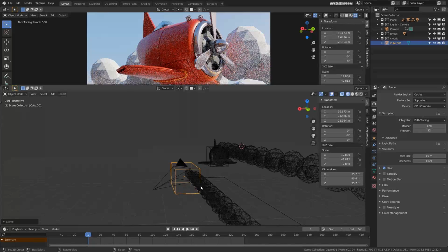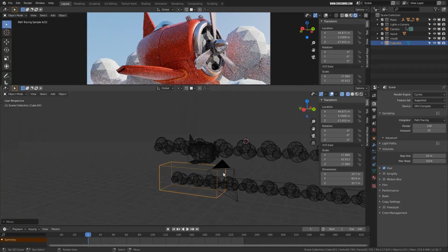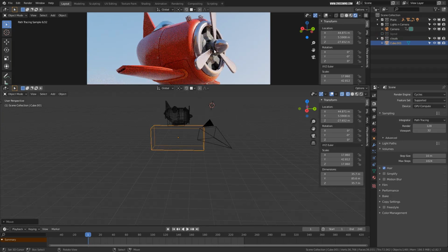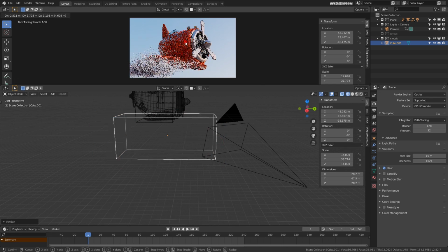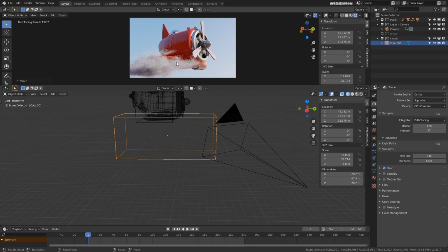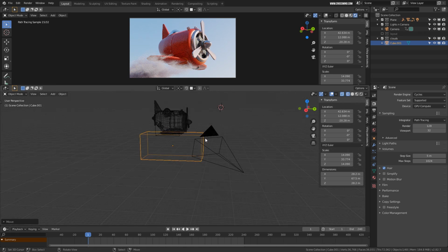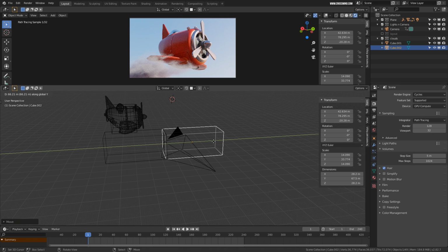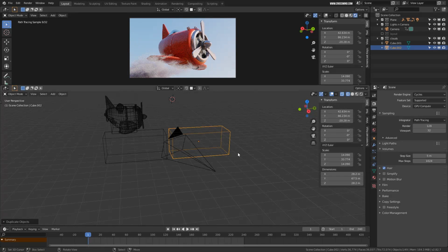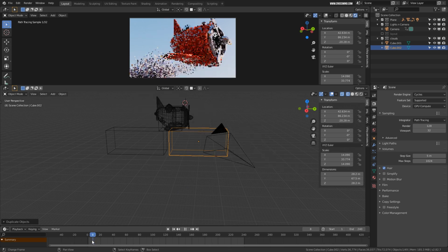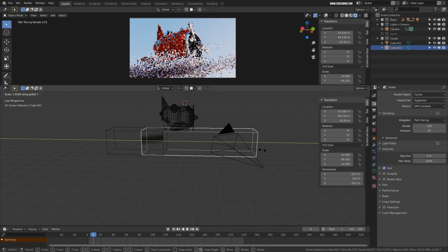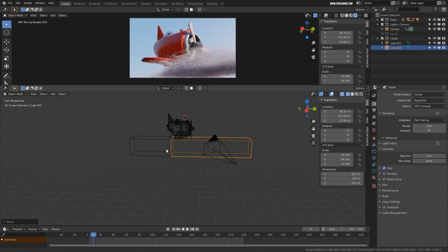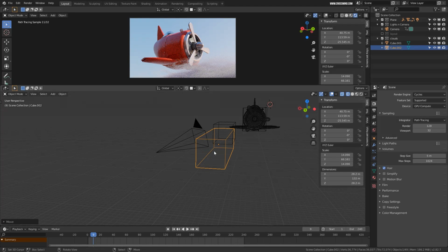Now let's add this cloud over here. Okay, disable the layout and frame it over here, something like this. Scale it down if you want, and let's make it 5 steps for now. Now what you can do is make a duplicate of this one and place it over here, so that when the camera animates, you'll have multiple clouds if you scrub the timeline. Also you can stretch it in the Y direction and move it downwards, and maybe give it some random rotation like this.